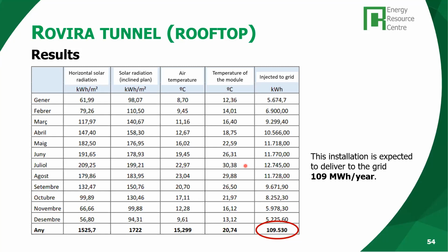Yeah. The most important is the level of irradiance. If you remember in the solar curves on how a PV module works, when there is a higher rate of irradiance, the IV curve of a module goes higher. The higher the solar radiation, the higher the current that is produced by a module.